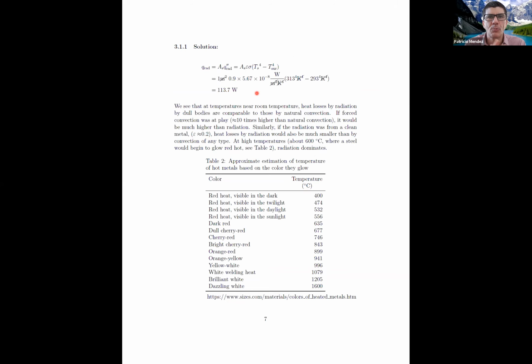Most of you must be familiar with thermoses, and I hope not all of you have broken thermoses, but I have. You get to see that inside they have this double wall, and this double wall is shiny, like chrome plated. And the reason is that in this double wall, sometimes they pull a vacuum, which is a good thing, and sometimes they don't. But in either case, they would have either no convection, because in vacuum there is no fluid to move, or it would be radiation heat transfer.